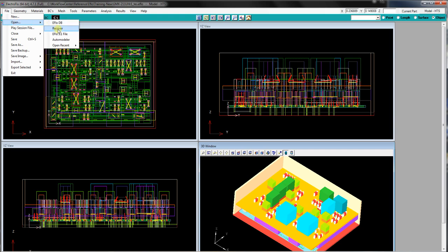Recover. This uses the CMod extension. This keeps track of the model after each command. In case the computer crashes at a point, you can restore your model by opening the CMod file. The undo files basically invoke the same functionality.